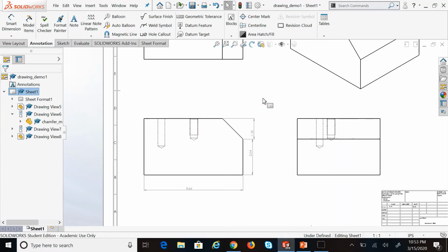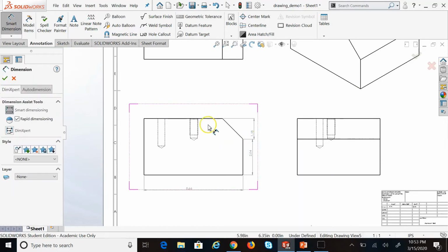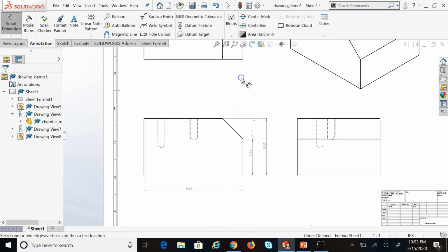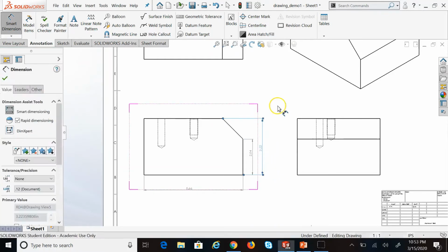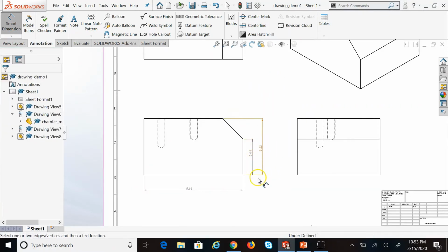I'm not going to do it that way. Instead, I would show the distance between the top edge and the bottom edge, which is the total length of the chain, and then I would delete this 1.18. First of all, I'm not going to show all three of them together because one of them is redundant, clearly. So I click on the last part of the chain and what? I delete that. This is how I show it. This is the correct chain method if I want to use it, which, in this case, because I only have two of them, is also similar to the stacked method.